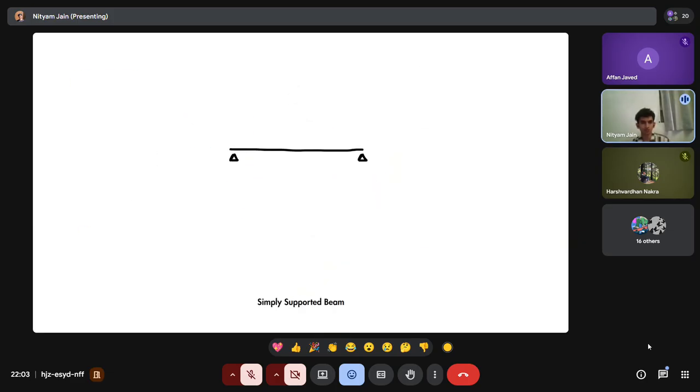If we take similarly a simply supported beam, like let's say a wooden beam, for it the bending moment diagram sort of comes like this, and even the deformation is exactly like this. These kinds of bridges a lot of people would have seen, because if you take a rolling wheel joint, which is given in highways and huge flyovers, that acts like a simply supported beam.